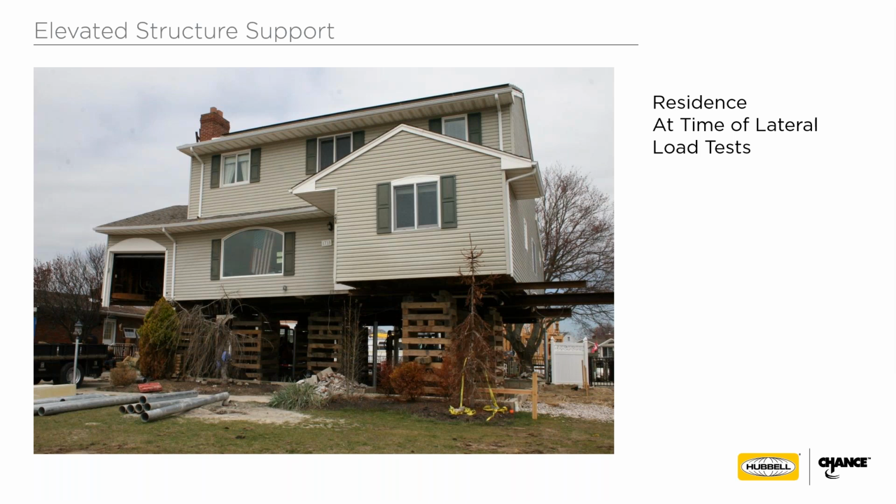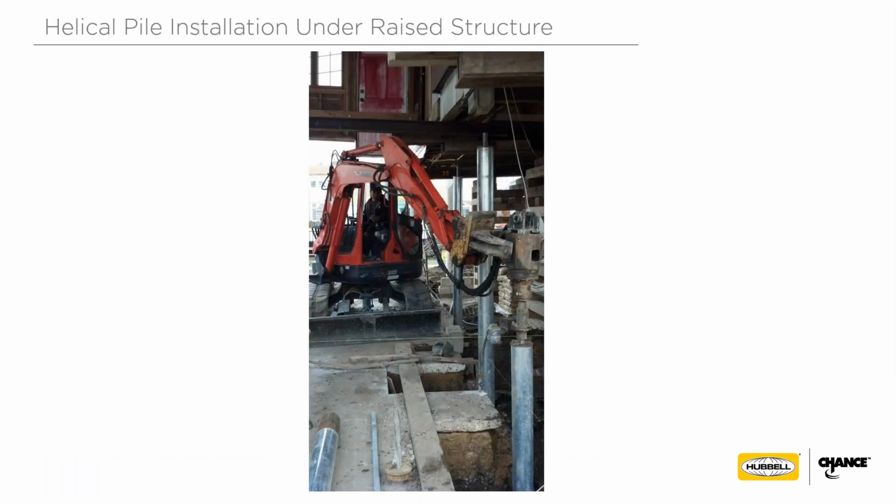Elevation contractor had lifted the structure, which is an art form in and of itself, as I'm sure some of you probably know. And so the contractor was going to start installing the helical piles underneath the structure as part of the overall elevation support of the structure. So here's an example of one of the attributes of helical piles. You're working directly under this elevated structure.